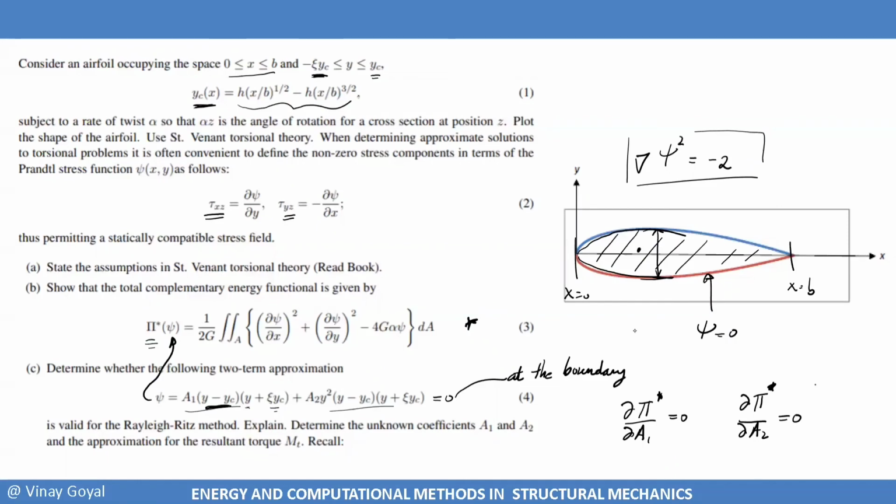So how could this be useful? Well, you can calculate the torsional constant for this beam. You can find J. Normally in aerodynamics, there's a moment that's acting on the aerodynamic center. And usually there's a coefficient associated with that which can be found through wind tunnel testing. So it can be useful because it can explain to you what is going on, what the value of J is for this cross section, and can also apply for other problems.